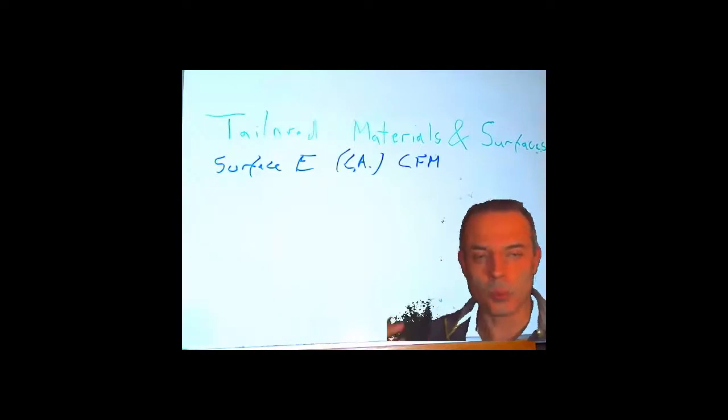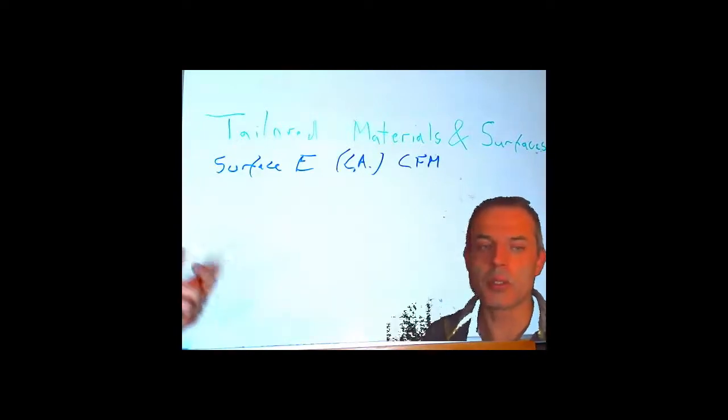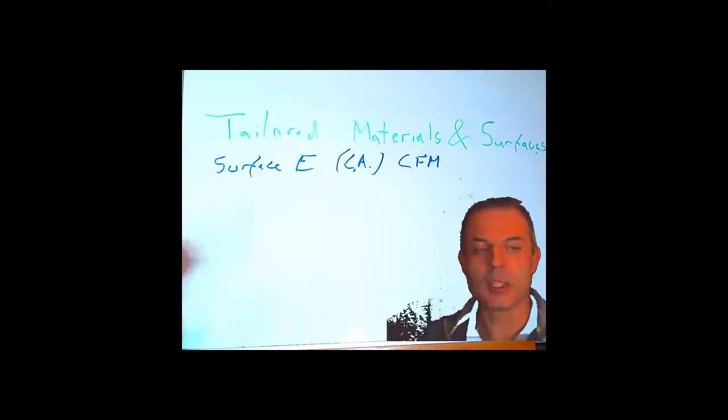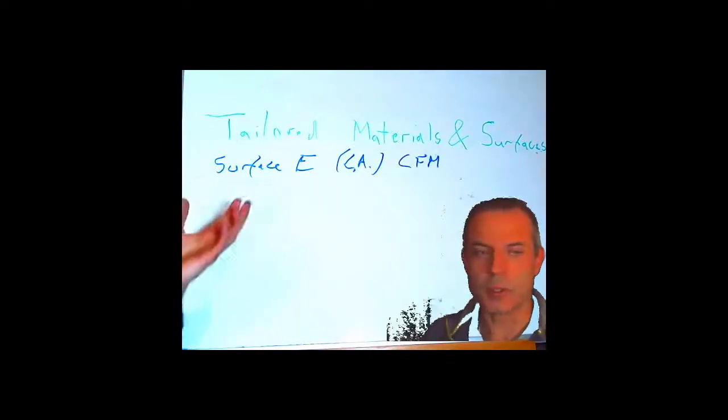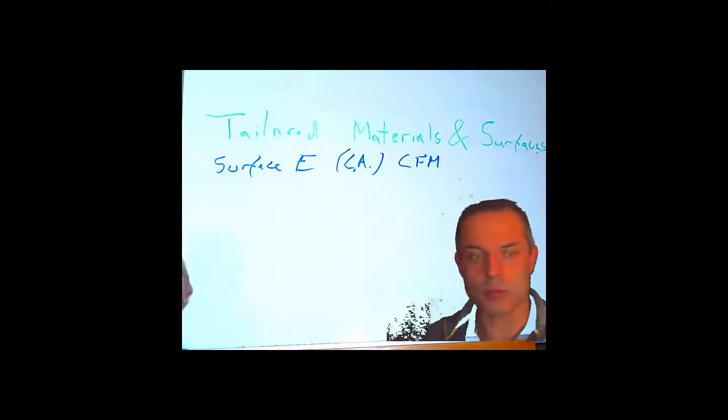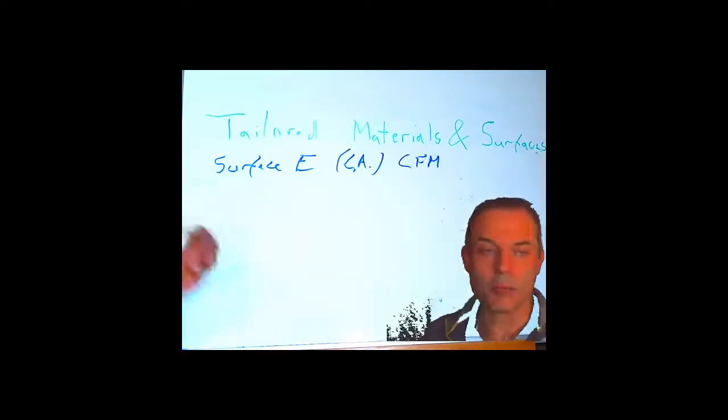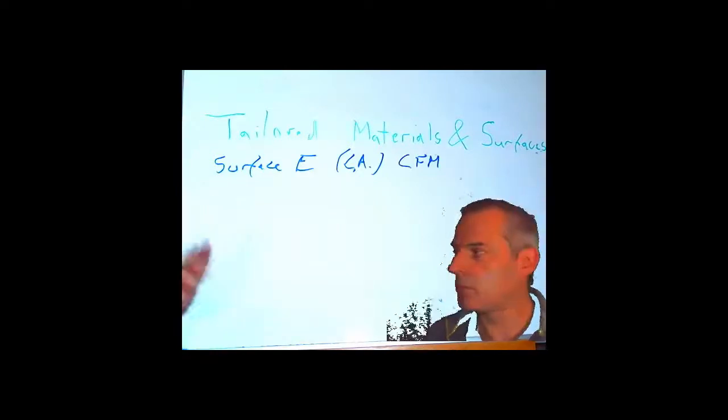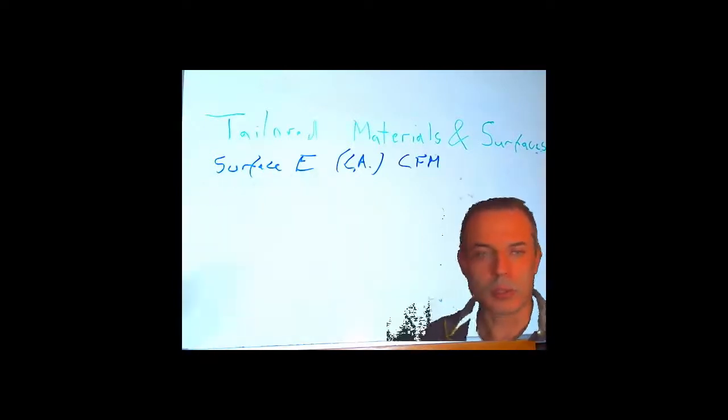Obviously, we will have to take multiple measurements, just as with contact angle, to remove any factors like roughness that will interfere with our measurement. Maybe the softness of the surface will also cause trouble. If we measure a range of liquids or contact surfaces, then we will be able to extract some kind of information on the surface energy.